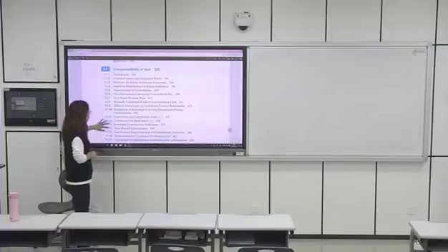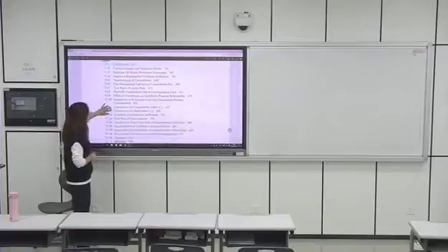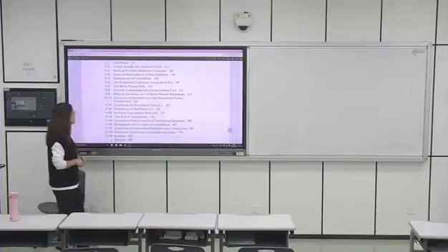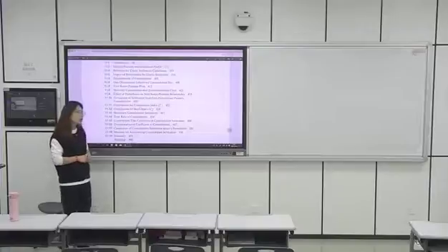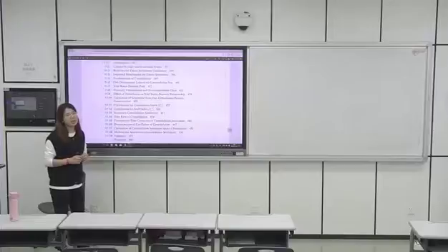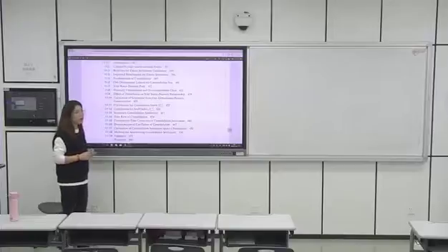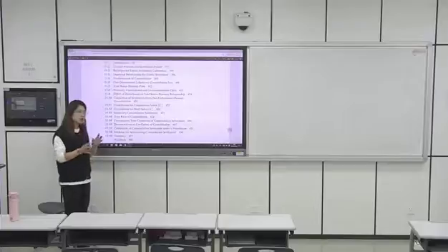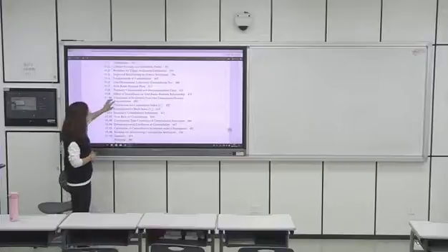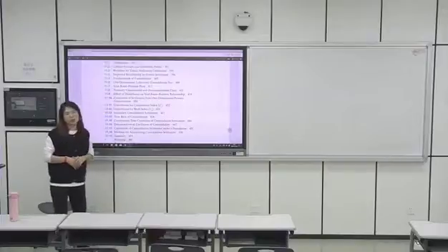And later we explained how to calculate the settlement for the one-dimension primary consolidation. Use the void ratio pressure plot. Actually, we need to use Cc right here. But if the applied pressure crosses the pre-consolidation pressure, we need to also consider the flatter part, right?